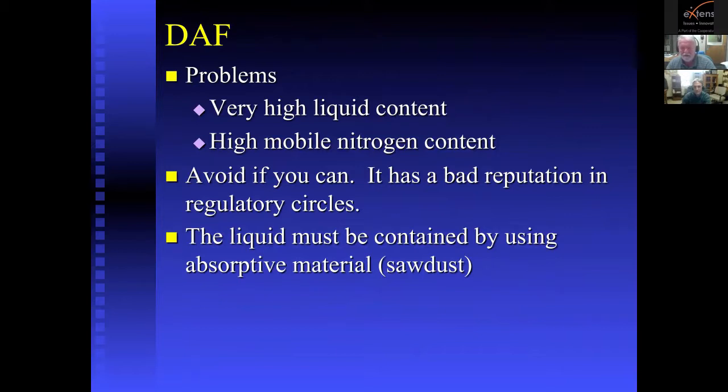Let me explain that a little more carefully. The nitrogen can get into the groundwater. It can run right out of the bottom of any compost operation if you're not careful. My advice is to avoid DAF in your compost operation because it has a bad reputation in regulatory circles. If you're going to compost it, you have to contain that. One way I've seen it contained is in a concrete pit that had a sloped side where a front end loader could take front end loads of chips, put it into the pit, mix them up until it was no longer dripping water, and then carry them off to be put in a compost windrow. But they had to mix it in the concrete lined pit to contain the DAF. So that pit was built specially for disposing of DAF in a compost operation.